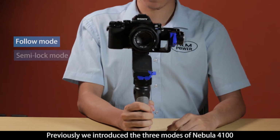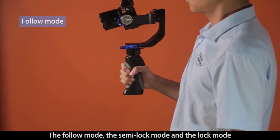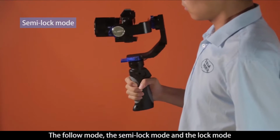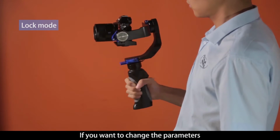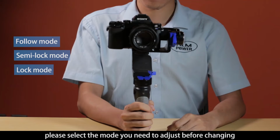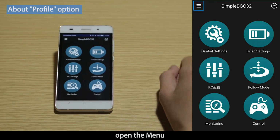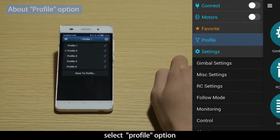Previously, we introduced the three modes of Nebula 4100. The follow mode, the semi-lock mode, and the lock mode. If you want to change the parameters, please select the mode you need to adjust before changing. Open the Assistant app, open the menu, select Profile option.